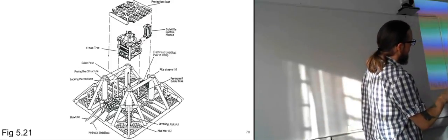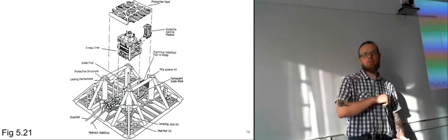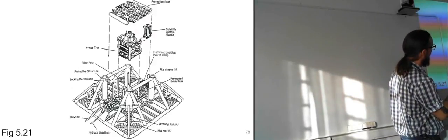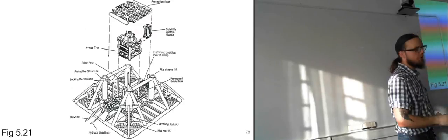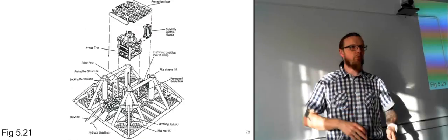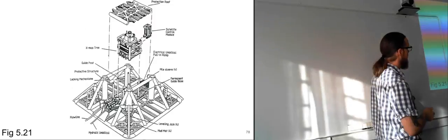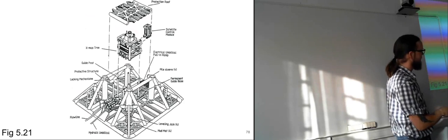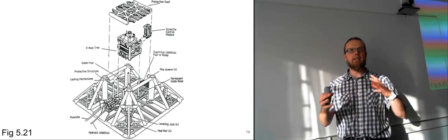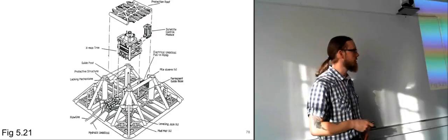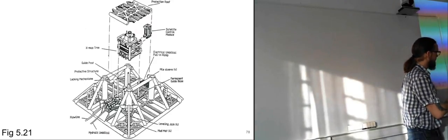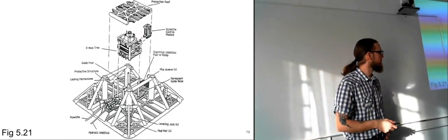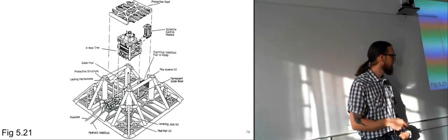So this is a structure which is there to protect this equipment. You can see that it has a protection roof that will come down on top of here to protect it from the top, so that an anchor won't drop right down on and hit the Christmas tree directly. And it also has all of these bars going on the outside in order to try to avoid anything snagging the Christmas tree itself and pulling on it. So it would snag the structure, but the structure is built to handle it if a ship snags it with an anchor or a trawl or anything.